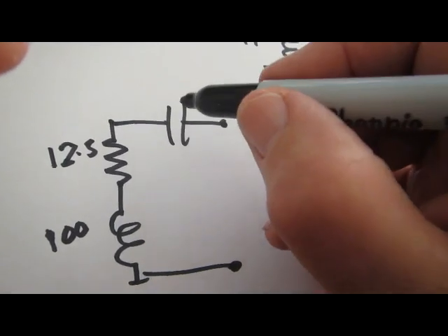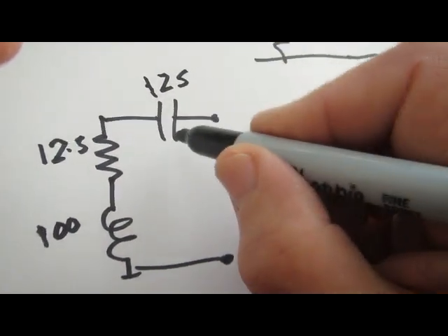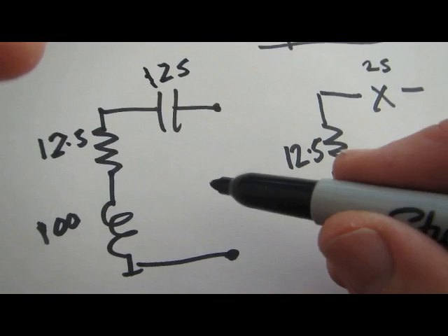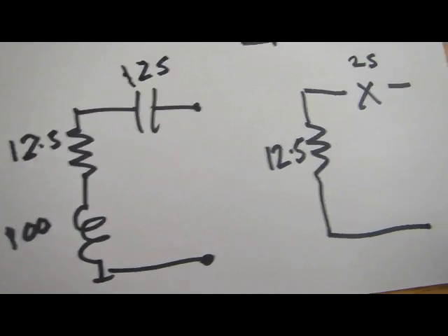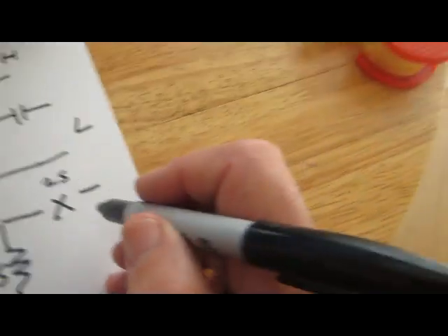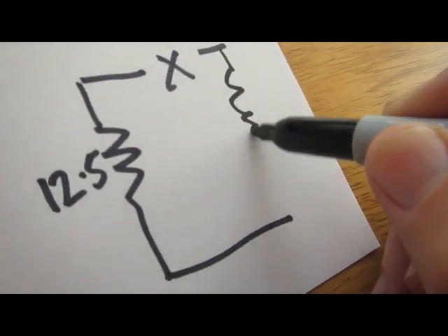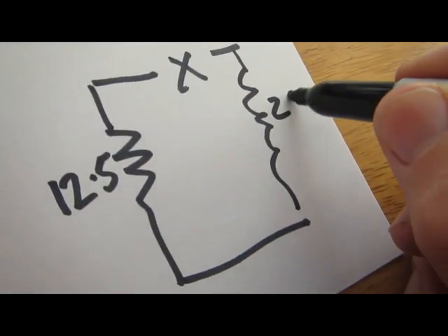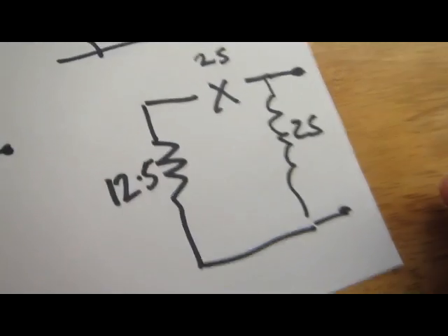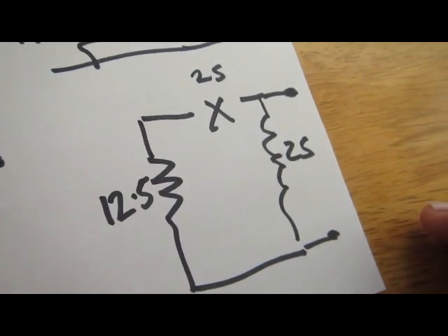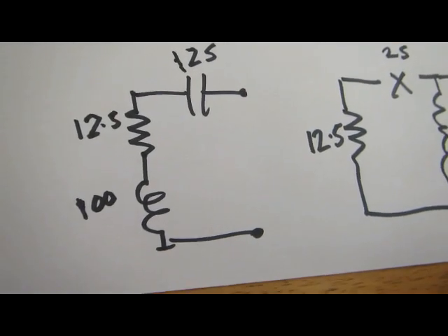So if I put in 125 ohms, these two just deduct from each other, their opposite sign. That gives me the 25. So I need 125 for my network, and that gives a total of 25. And then eventually, to finish the job, we put this across here, which is 25. And that will give us our 50 out, the same as I had on the previous example. So we mop up the reactance of the load into the first element of the L network.